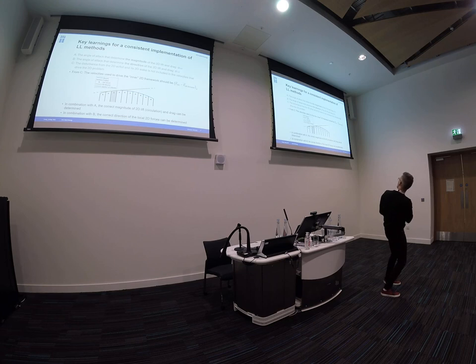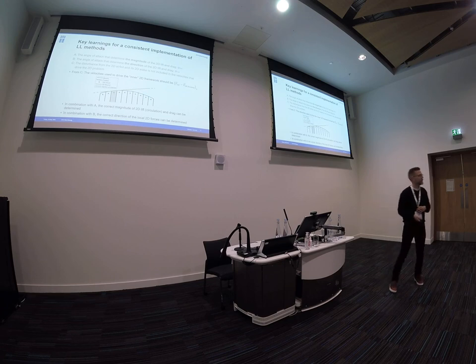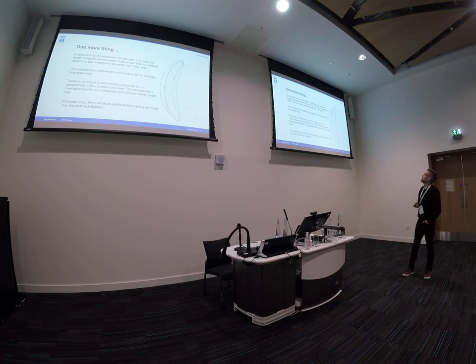Let's say this is the interesting section, and then to get the important velocities that drive the behavior of this section, you need to subtract the influence of the green vortex, the 2D vortex there for that section. And this is the way. If you do that, then I'm happy, because then it corresponds to what thin airfoil theory says. So, and then there's one more thing.